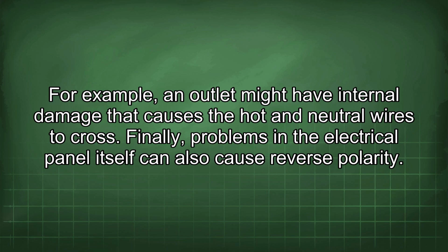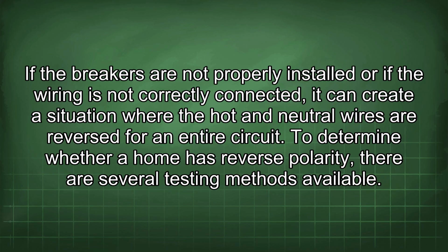Finally, problems in the electrical panel itself can also cause reverse polarity. If the breakers are not properly installed or if the wiring is not correctly connected, it can create a situation where the hot and neutral wires are reversed for an entire circuit.